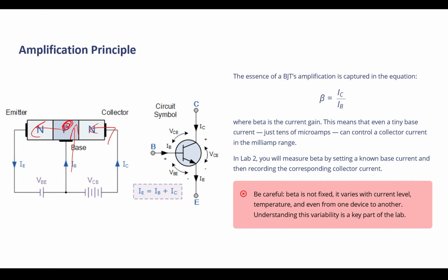In a MOSFET, the gate would not participate in the current because it was isolated. Here we are directly connected, so we participate in the current. So if you wanted to be precise, the emitter current is equal to the summation of the base current and collector current. But why do we say the emitter and collector currents are approximately equal?